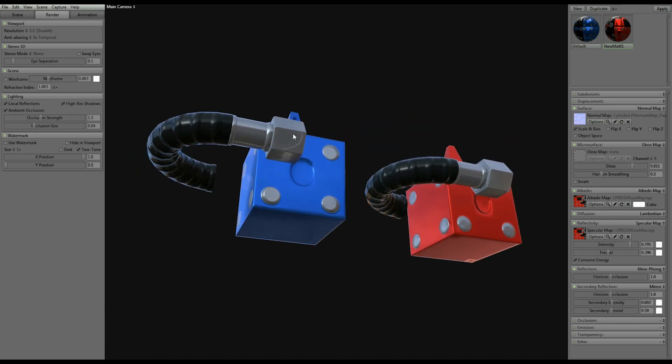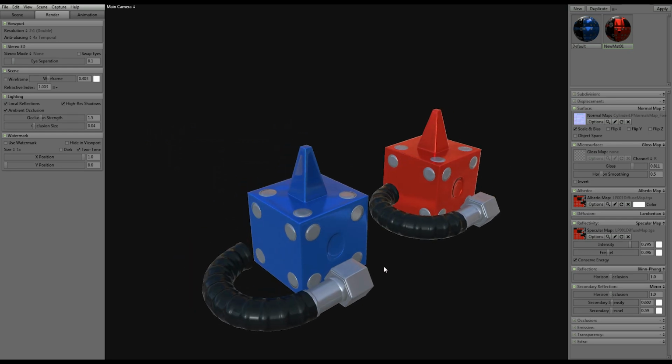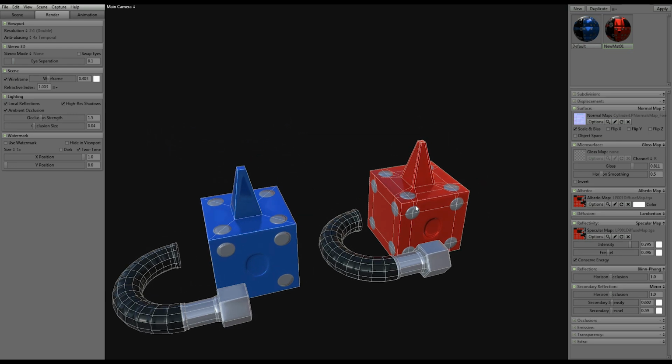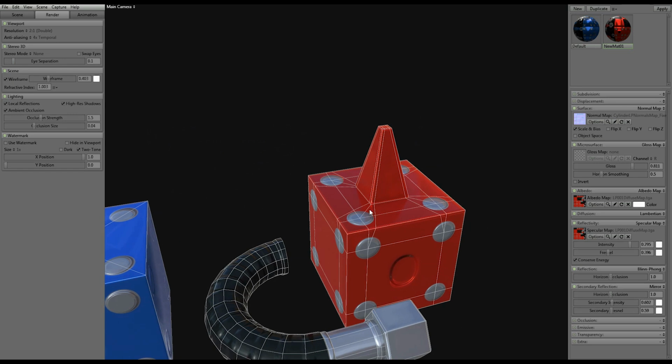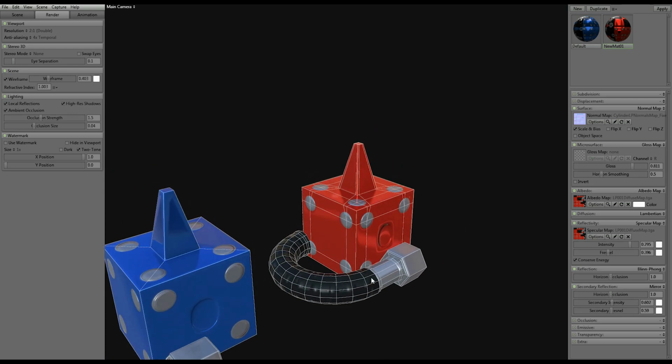From here to here isn't a 90-degree angle, not even really close to it, and the rest of it's just a cylinder or a tube. So that's the rundown of what to look for. Once again, adding supporting edges like how I have it here with vertices, or separating the smoothing groups, are the two main ways to remedy the problem. But that pretty much wraps up the section of the tutorial on how to solve baking issue